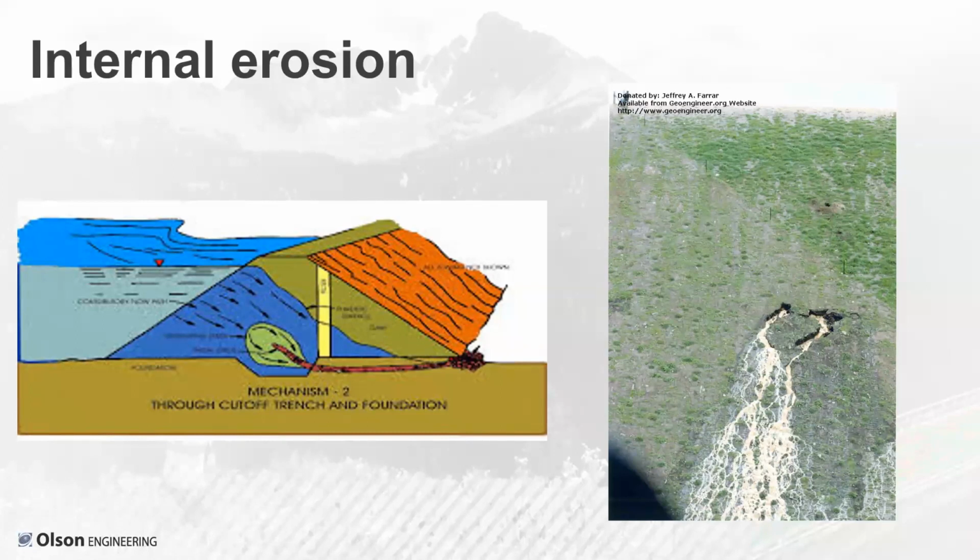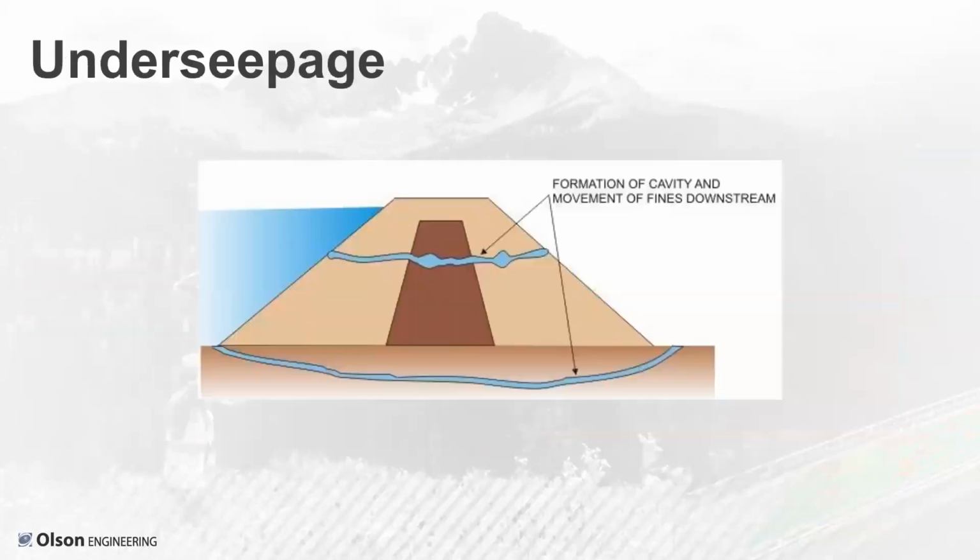And as that water is coming out, it generally starts to carry material with it. Typically, we're worried most about the materials that are on the surface of the dam. And then eventually we can have some clay from the core getting through. And what will happen is as enough material moves through, that flow path can increase in size such that a failure can occur on the dam.